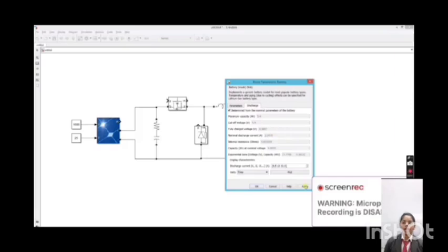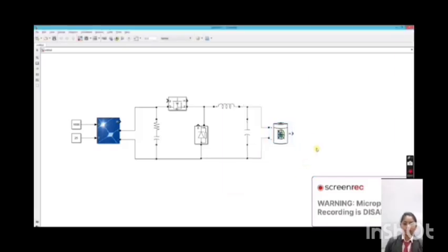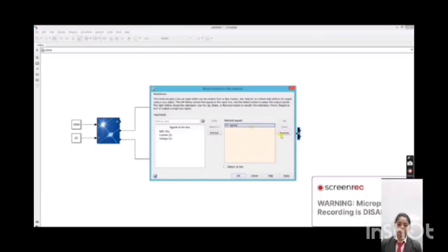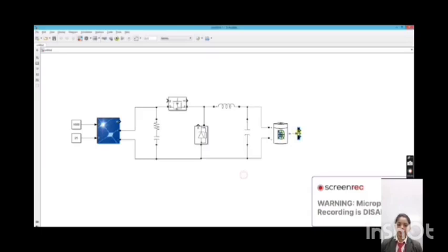panel, and the buck converter steps down the high voltage from the PV panel to match the charging voltage required by the battery. In simple terms, it reduces the voltage while increasing the current. This is critical since the battery can only handle a specific voltage range. Set the charging voltage of the buck converter using pulse width modulation, PWM, to control the switching component and adjust the output voltage accordingly.